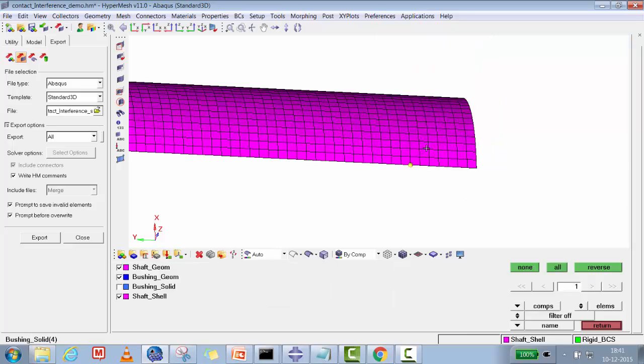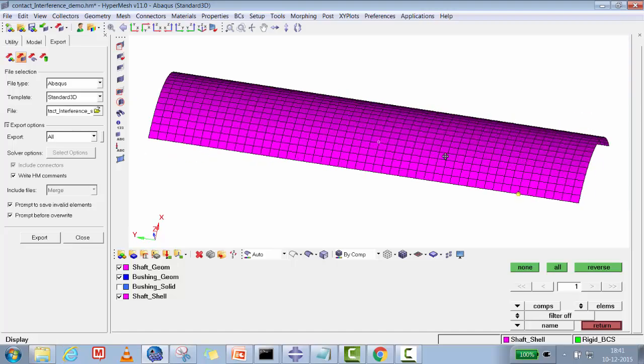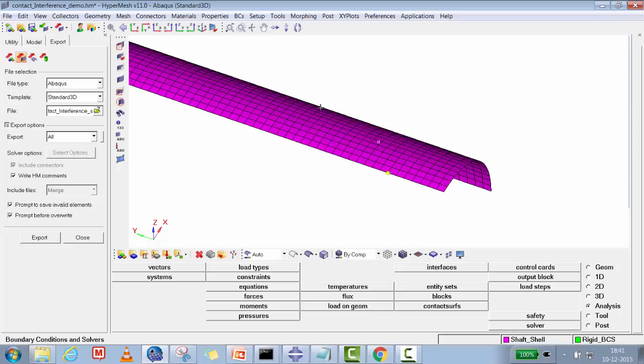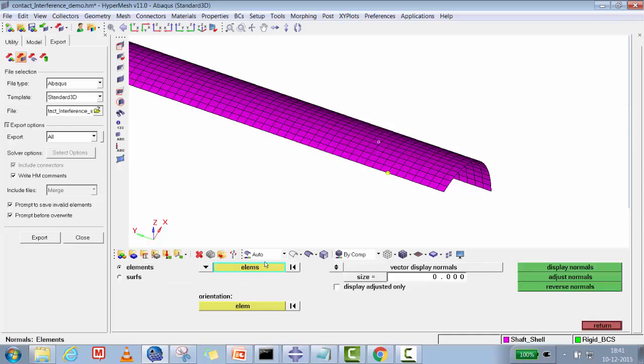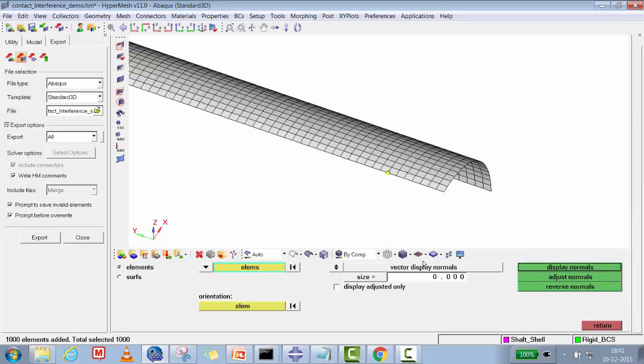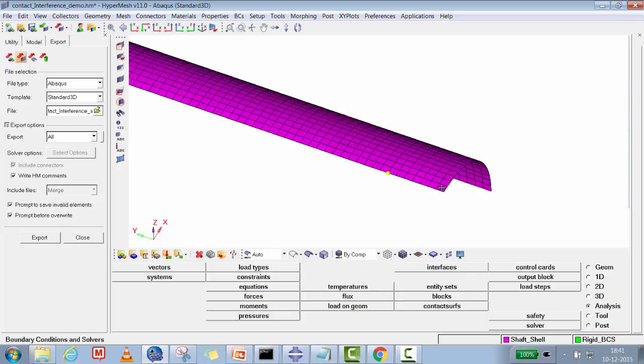So I just took some reference node there, put a temporary node where I have to put it, and then I'll check normals. If you press Shift F10, you'll see a normal, and there you'll find a panel where you can get this normal. Actually I'm from the old simulation school, so I use all these shortcuts. So this is actually the outer normal.